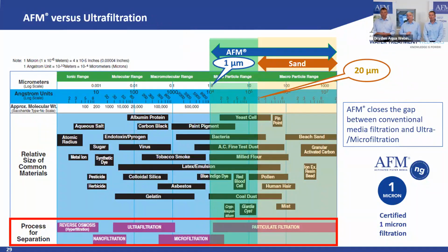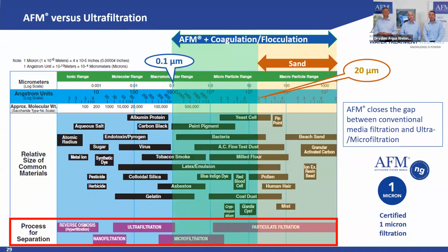Without coagulation flocculation. If we then add some coagulants, and maybe flocculation too, we can really remove particles down to 0.1 micron. We are in the range of ultrafiltration. It doesn't need a lot. And on top, we remove substances which are in solution, like phosphates, and also humic acids. If you don't have phosphates in the water, you don't have biological growth. So again, UF is absolute, we are nominal, but nominal down to 95%.